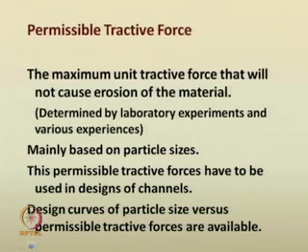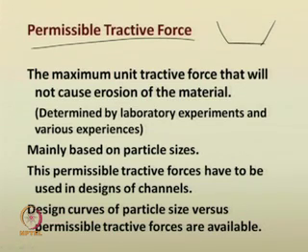The next topic we are going to go through is permissible tractive force. So, what is meant by permissible tractive force? It is the maximum unit tractive force that will not cause erosion of the material. As we are dealing with unlined channels, erodible channels means unlined channels.